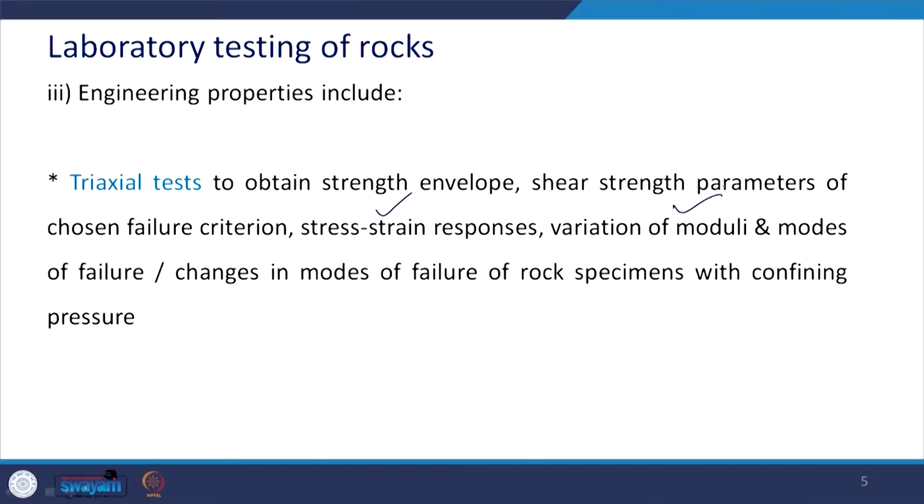Then along with the strength characteristics, it gives me the stress-strain response, variation of moduli, what the various modes of failure are, very important, and what changes happen in the modes of failure with the confining pressure.